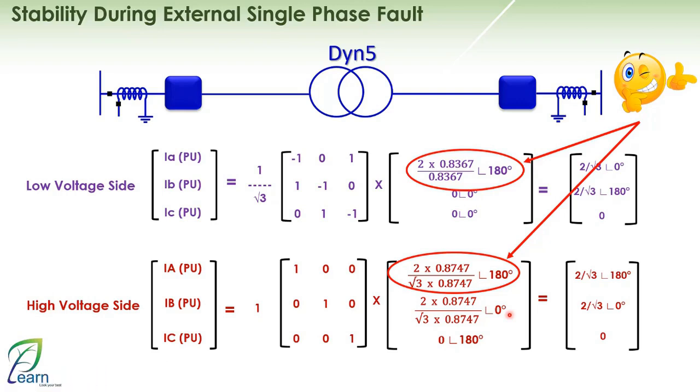Well, I have 2 mistakes. The first mistake is that you ignore the vector group of the transformer. I have a Dyn5, so the phase on the star side cannot be opposed by a single phase on the delta. It must be opposed by 2 phases. Number 2, with this connection, we discover that even if you inject incorrectly, I don't have a problem. You will inject a phase and oppose it with a phase at a 0 angle, and change the current until it gives you a trip. So this part is very important to pay attention to.